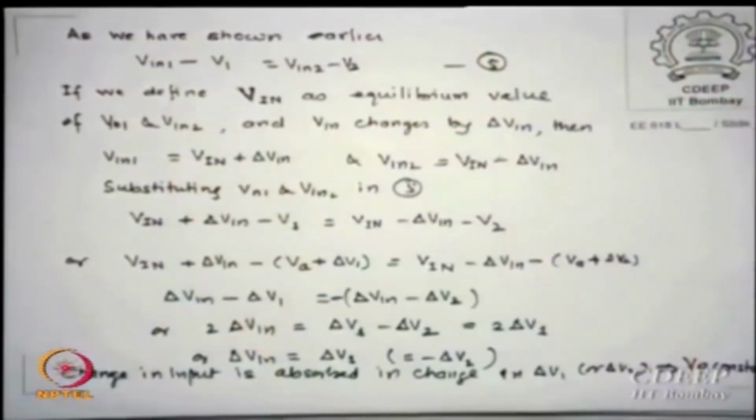Based on this, once I have declared a diffamp, I can always assume that a change in Vin1 is compensated, or an opposite change will occur, in Vin2 for a differential stage. In that case, I will now solve a diffamp using two separate parts of the symmetry, one left, one right, solve the outputs independently and subtract, and figure out whether I get the actual diffamp values which people say is the value.